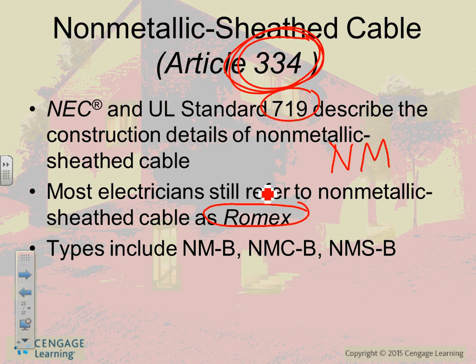It's the most economical way of wiring dwellings or wood buildings, any type of wood building. It's not just dwellings. Anytime you have a wood building, they call it construction type 4 and 5 typically, which is made out of wood studs. You know that wiring method. If you have, I don't know, a strip mall made out of wood, you can wire this. If you're engineering a project, you don't use this. You use MC cable. So just be aware of that one.